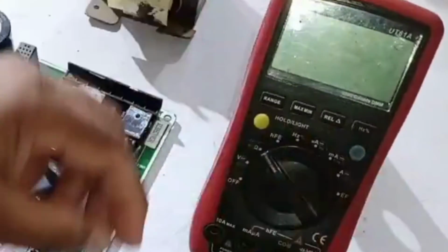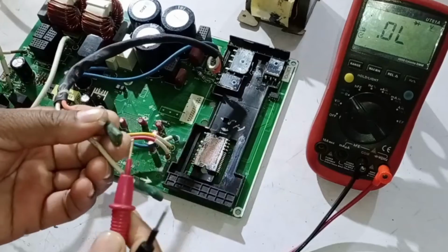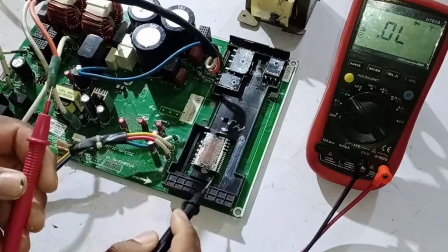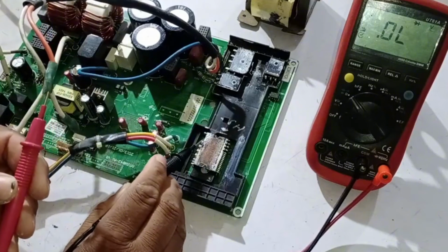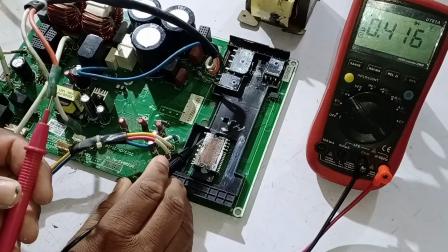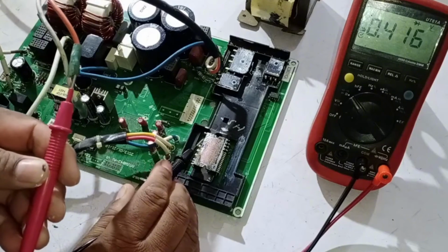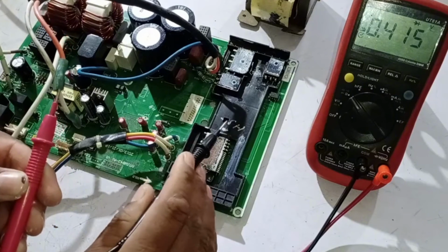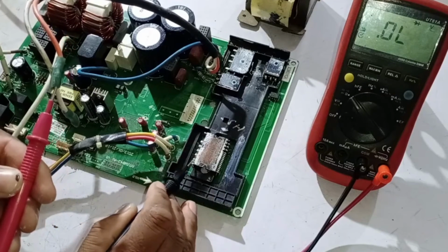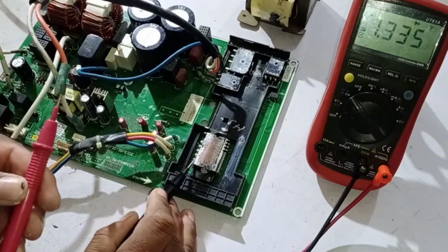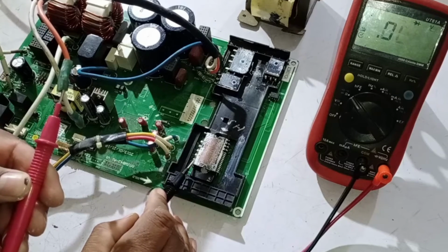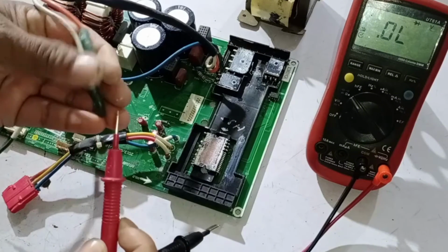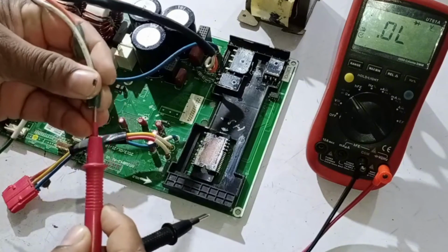First, take a multimeter and set it to diode mode. Connect the red probe wire to one of the reactor wires. Now, attach the black probe to the positive pin of the IPM. The multimeter should show a voltage drop of around 0.416 volts, indicating that everything is working correctly. Next, attach the black probe to the negative pins. You should see some voltage readings appear and then disappear, which means this point is also working fine with no issues. Now, switch the red probe and attach it to the other wire.